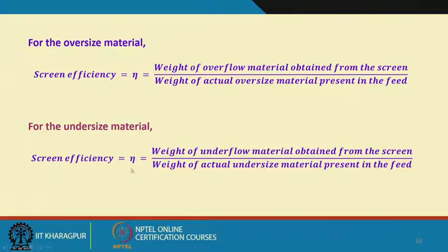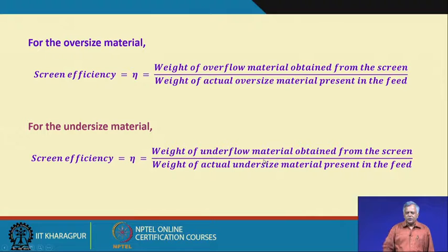Similarly, for the undersized material, the screening efficiency can be defined as the weight of underflow material obtained from the screen, how much you have got, over how much actual undersized material was present in the feed.